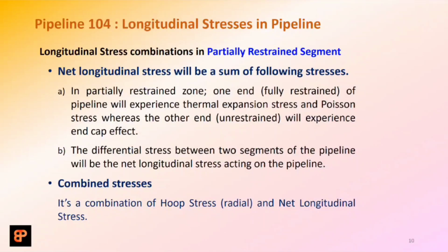And if you compare that with the results given by the stress analysis program, the Caesar model, you will understand that around a similar length, your Caesar program will also show you that the displacements are becoming zero, so the fully restrained zone is getting achieved. So this will allow you to calculate the virtual anchor length, which we can develop later.